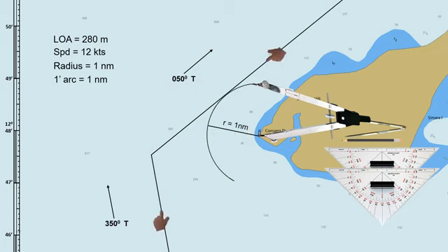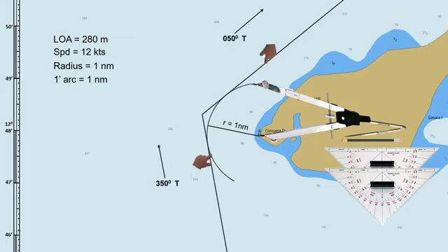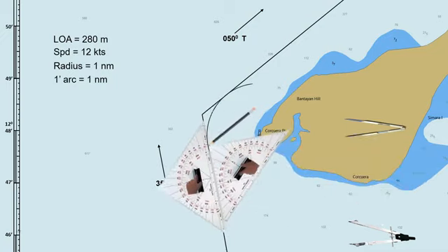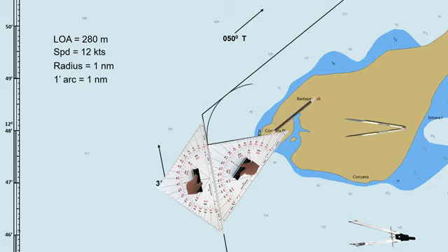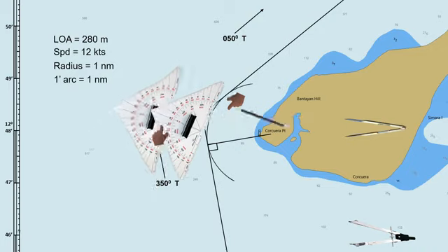We will now transfer the previously planned route along the arc. Both tracks should be touching the edge of the drawn arc. We have now a clear view of where the ship starts to turn, and to where it ends, but we need to determine the exact point. Draw a line from the lighthouse. This line should be perpendicular to the planned track. Do this on both tracks.